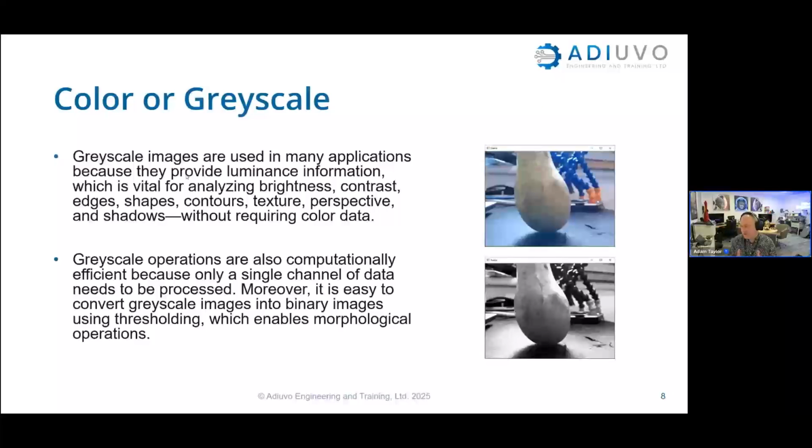So we can have a much reduced number of bits to transfer the image, which means we can fly that through the FPGA faster. If we're buffering things within the FPGA, we need less memory, and it reduces the complexity of doing any calculations on it, because we're only working with one channel, the luminance channel. So it's a very, very powerful thing.